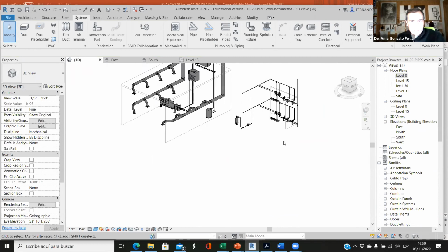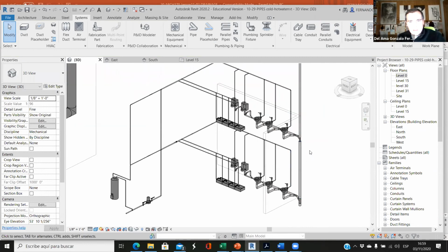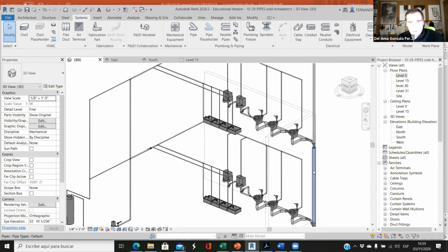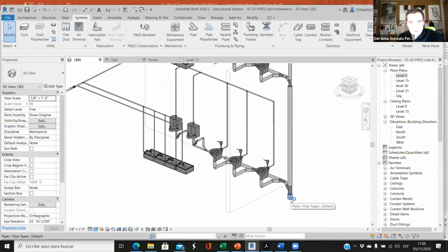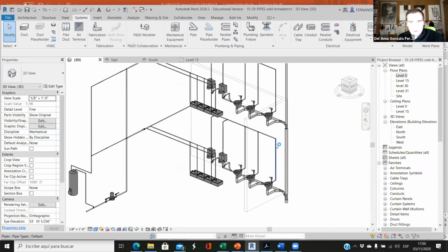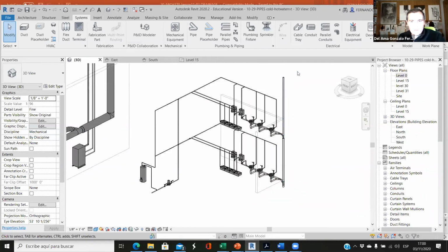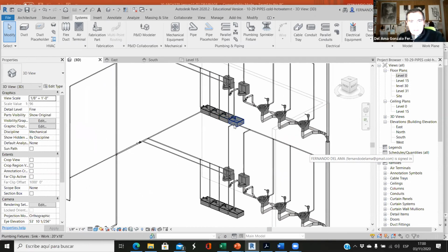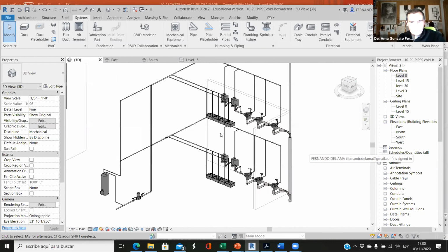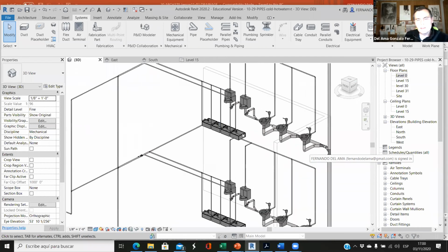So now we are done with the soil stack. We have connected all toilets and the urinals to the same vertical pipe. It goes underneath the floor level. It goes above the roof level for the vent. So now it's working well, and this is all we need. And now we need another stack for the sinks. Okay, so let's do it.